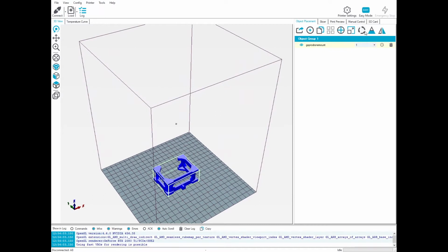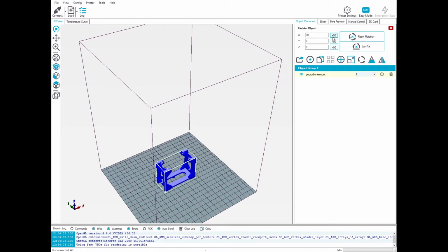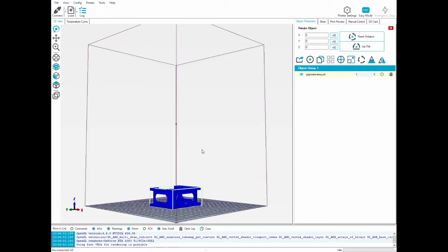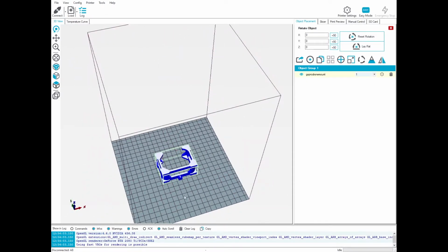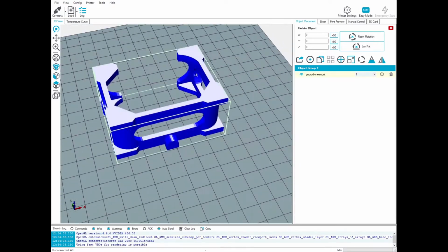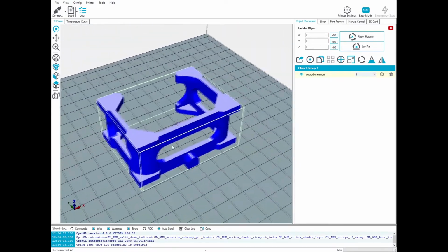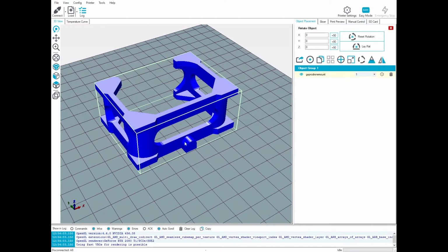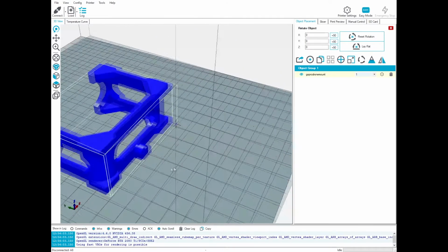If you have any need to rotate or otherwise, you can sit there and click these 90-degree rotation increment buttons and move the part around. This part was designed specifically to be printed in that orientation. You notice this tab down here at the bottom sits nice and flat and flush with the print bed. To avoid support structures wherever possible, you want to avoid overhangs wherever possible.